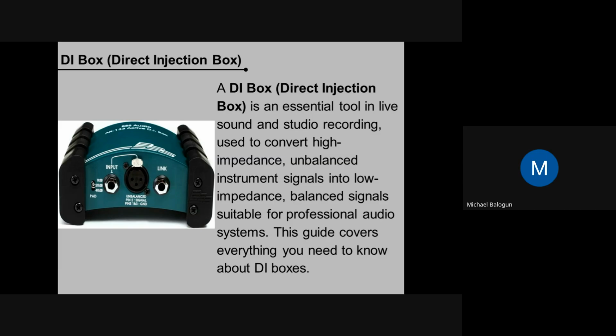I found myself in a situation where I used a DI box because of too much noise. If you have to slap the DI box, that means your DI box is sick, it needs to go to the doctor. It's faulty. However, don't quote me wrongly. Even if your cable is bad, and you use 20 DI boxes, it will still have the noise.